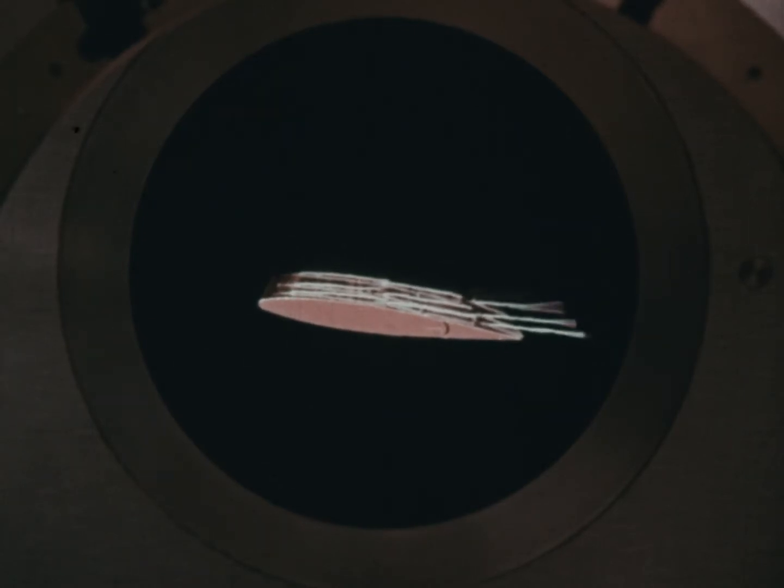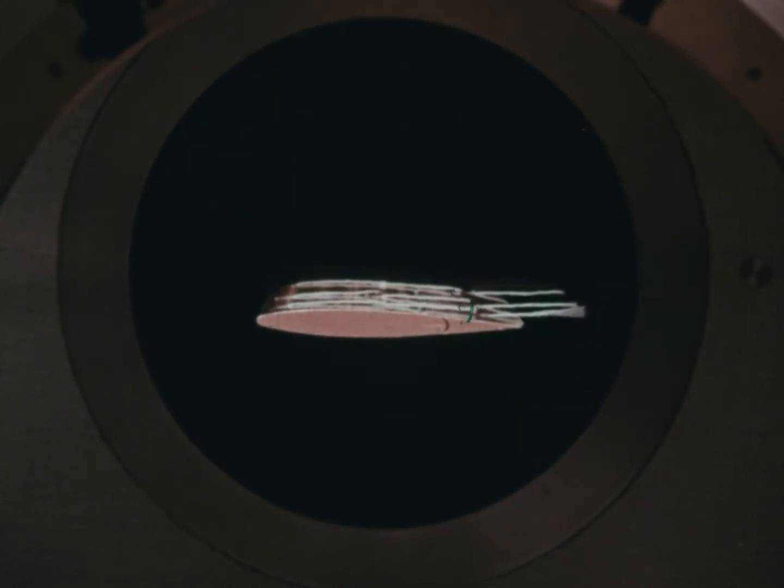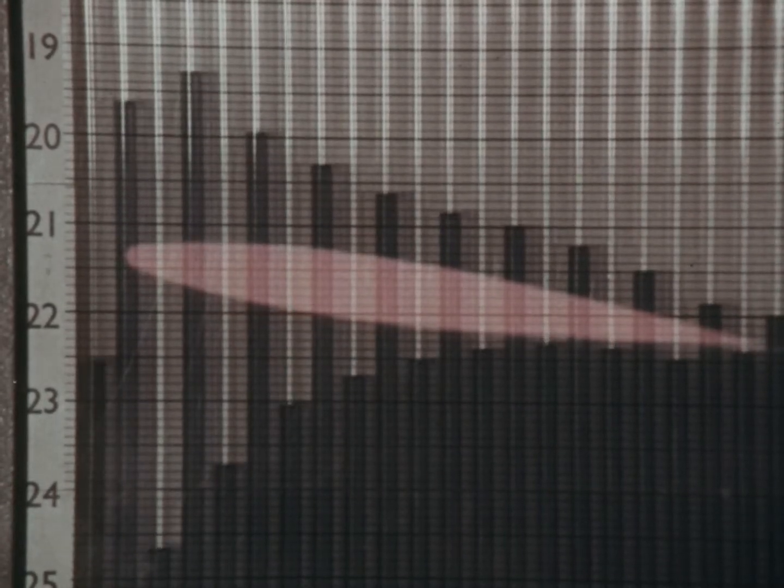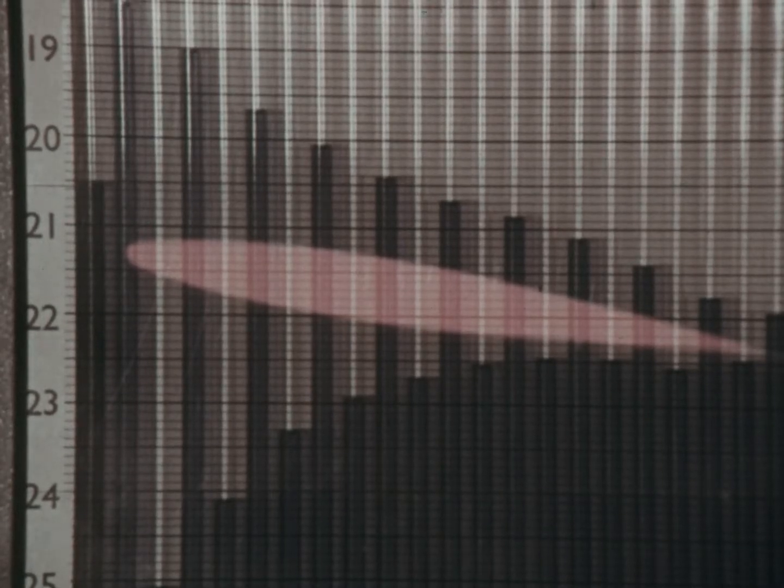Here is the wing section with wool tufts to show us the airflow. Now let's superimpose it on the manometers and see what happens. The manometers attached to the upper surface rise, indicating a considerable drop in pressure, while those attached to the lower surface fall, indicating a rise in pressure. And it is this difference between the pressures over the upper and lower surfaces that gives the wing its lift.